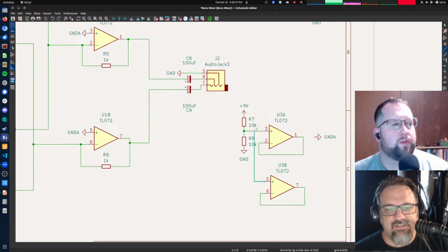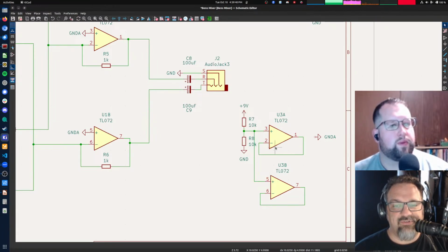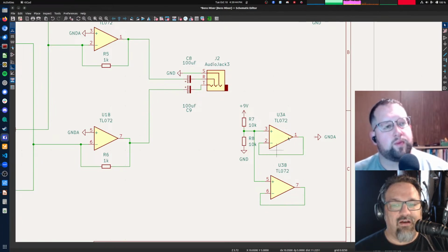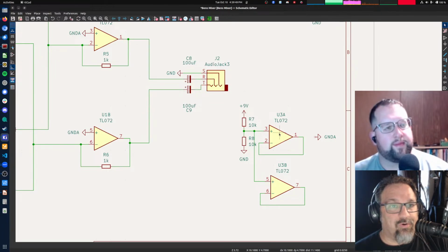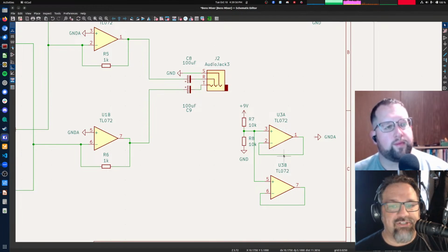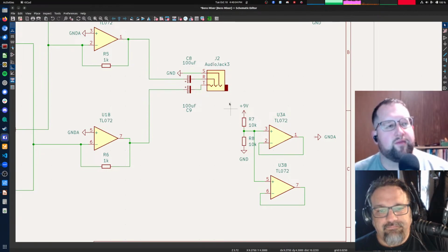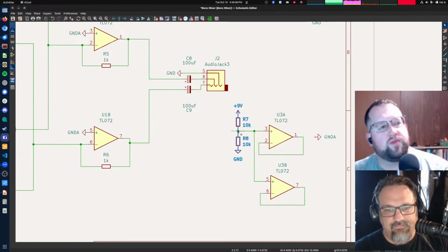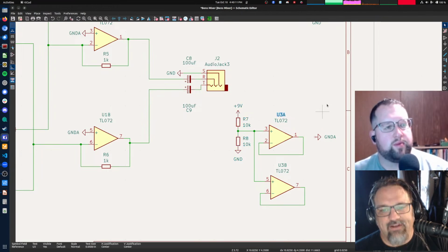So what I'm doing here is, because these op amps come in a package, and we have an extra one here that's sitting there doing nothing, we're just going to go ahead and put it in parallel with this one, and what it's going to do is double the current handling capacity of your virtual ground circuit. It's going to make it so that it can handle twice as much power. It's going to make it twice as good, quote unquote. But that's just kind of a freebie because we're looking at an op amp that would serve 2 circuits in the example here. Correct. Yeah.